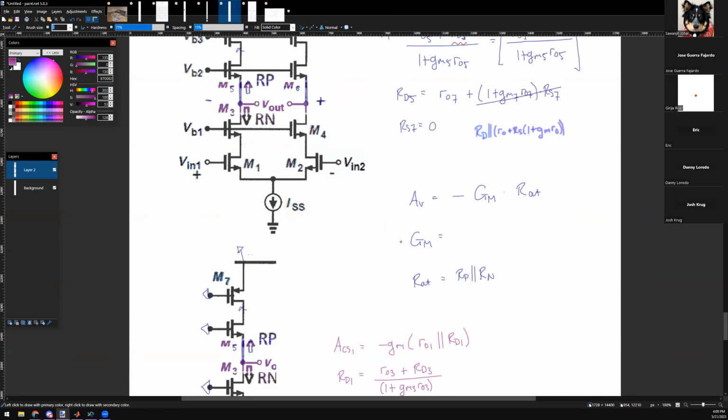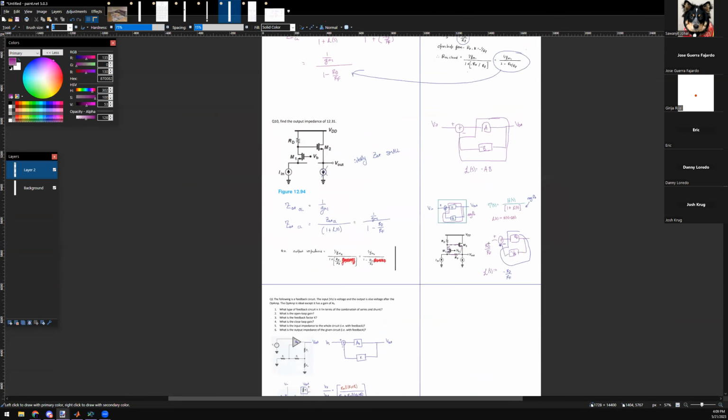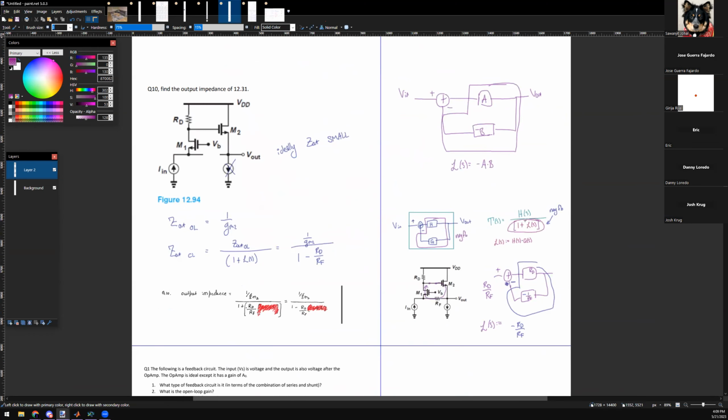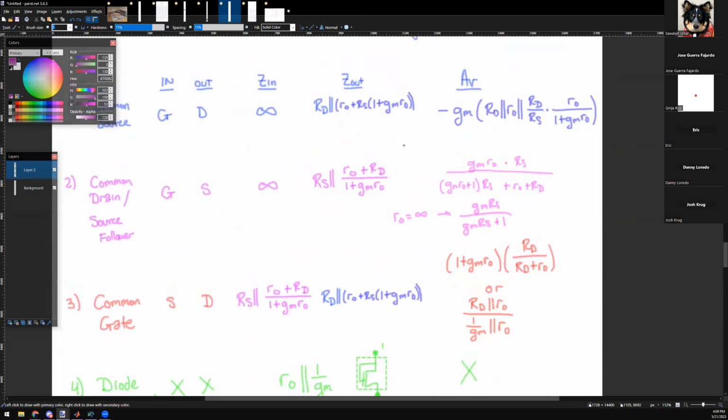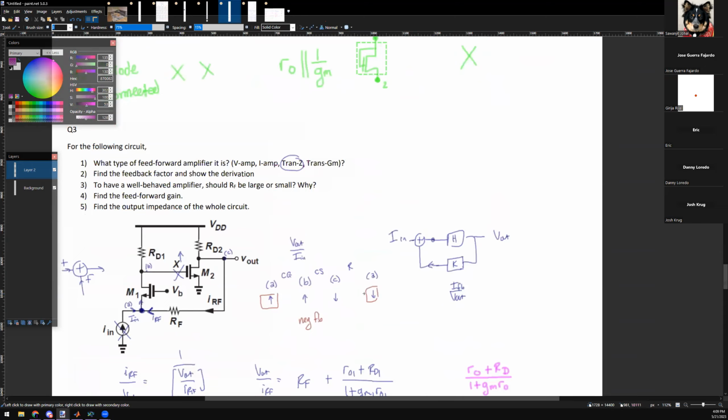You guys remember that loop gain factor that we talked about before, by the way? Remember how we said divide and multiply by this, 1 plus blah, blah, blah? For MOSFETs, the loop gain, if you look at my expressions, I always batch together the 1 plus GMRO everywhere. This is very intentional because I have been paying respect to this loop gain idea. So this 1 plus GMRO is like a bonus factor. Maybe not for this one, sorry. This one. It's that extra factor. I put it everywhere because it does belong there. That's what a MOSFET does.